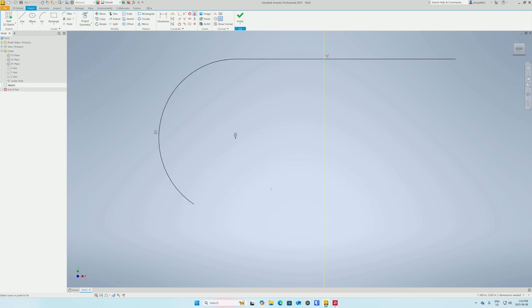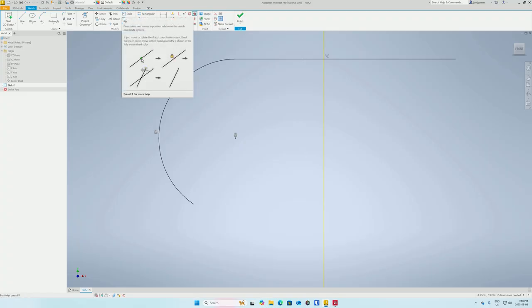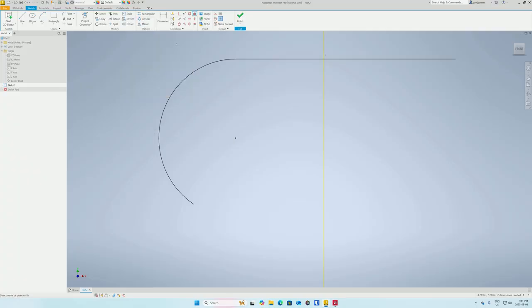It is a quick way if you're having real trouble to totally constrain your sketch, but then you don't understand what degrees of freedom you're missing. So I'm not a big fan of it. I don't use it myself much. Or if I have to get it done, then I go back and fix it later. So that's that one.